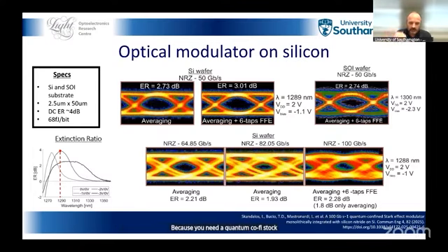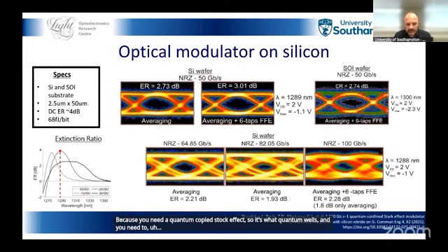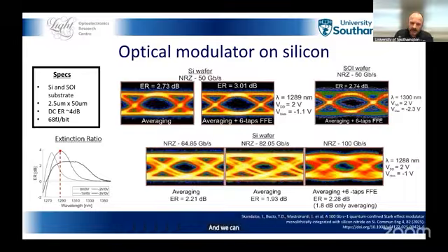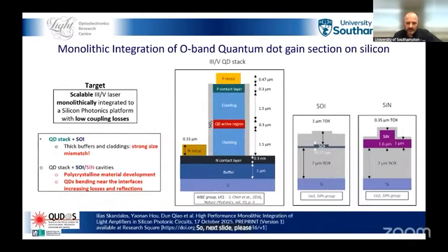So it's quantum wells, and you need to match lattice and reduce defects, right? But this is actually possible, and we demonstrated it at wafer scale, and we got 100G out of this. We can transfer the light from high index to low index with about 1.5 dB insertion loss and low reflection. So next slide, please.